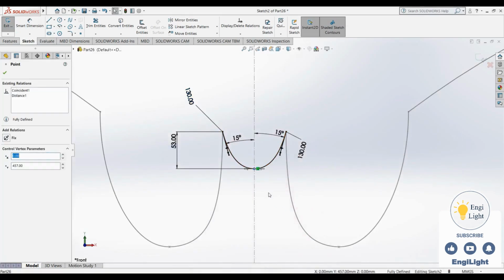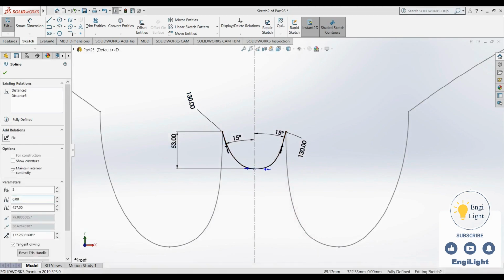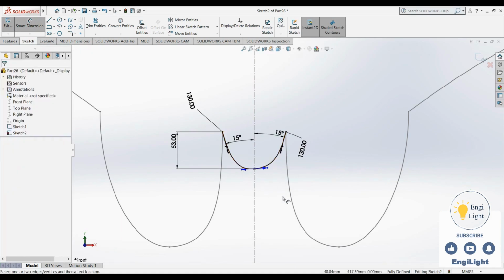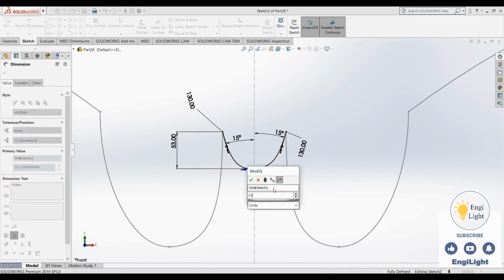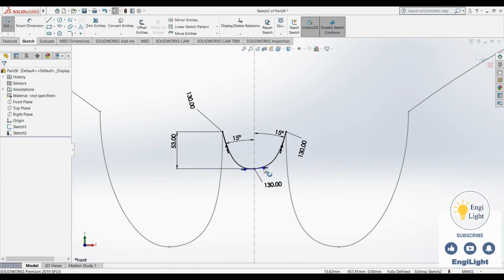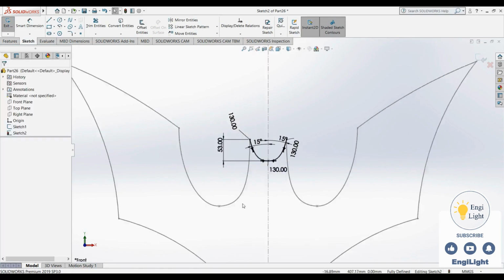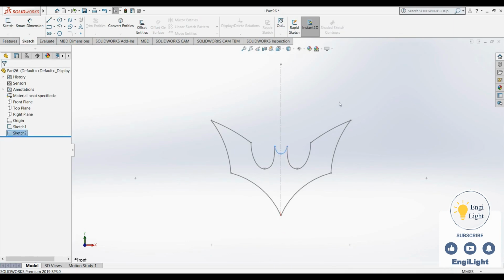Just like before, I adjust both handles towards 65 millimeters each. One's at 79 millimeters. I just pull it down towards 65 millimeters. Then, I set the total handle length to 130 millimeters. And I align it horizontally. And that completes the sketch.